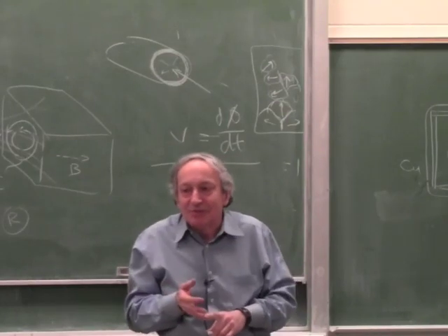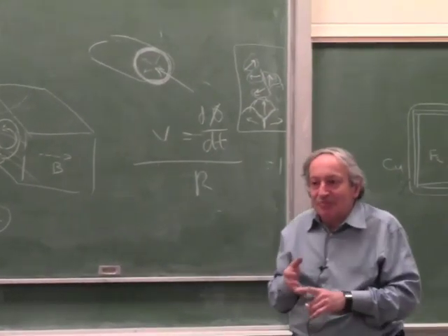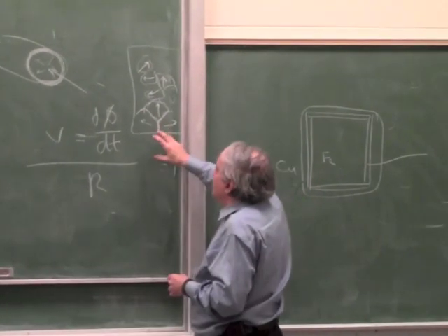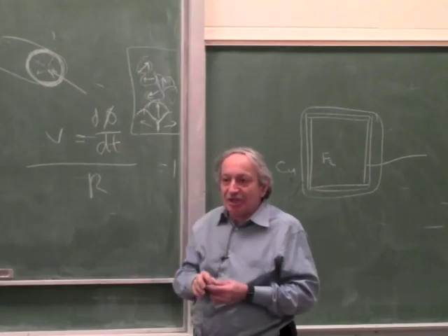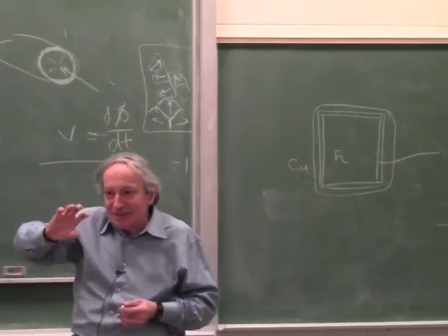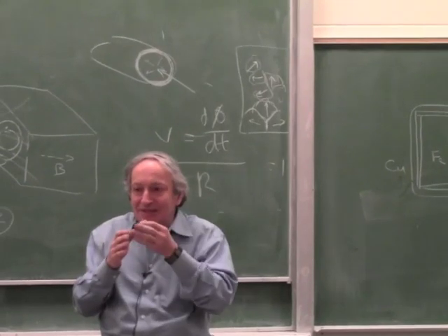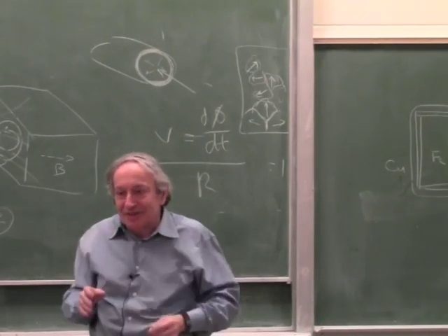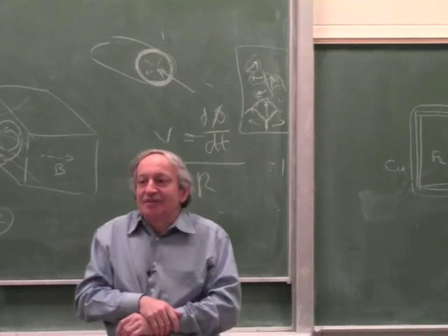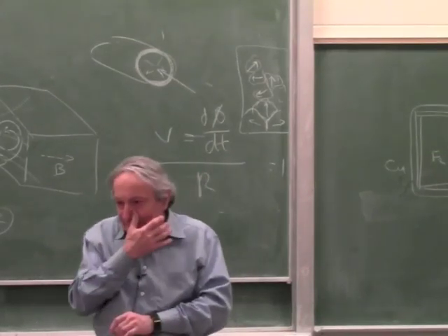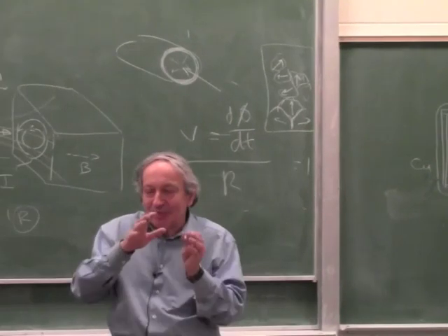But what really happens, the most noticeable effect, is that the boundaries of these domains change and the orientation of the domains changes. It doesn't mean the domain is physically rotating, but the boundaries where the magnetic lines separate shift, and they all line up. It's actually not a simple effect. There's the Barkhausen effect, which is a jumping of the domains, meaning they don't move smoothly, they jump.